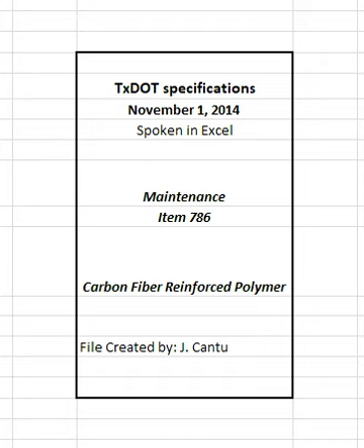3.7 Remediation. Epoxy inject behind CFRP layers where small voids and bubbles are located that have a nominal size of 3 inches or less. Analyze defect areas larger than 3 inches and perform repair work as directed, which could include removal and replacing portions or all the applied CFRP. Perform required remediation for pull-off test results failing to meet the required minimum as directed. 3.8 Protective Appearance Code. Clean and paint CFRP System 1 in accordance with manufacturer's specifications.